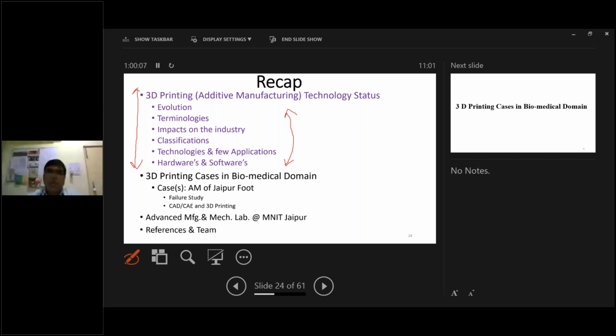Based on whatever scanner knowledge I have, the one limitation with scanners is the reflectivity of the light. If you have a material which is highly reflective, then it will be difficult. There are some powders which come along with your scanner. Just spray those powders on it, and then scan it. It should not be a problem unless the reflectivity is an issue, because this captures only the contours and the shape. It won't give you the internal material properties that you have to integrate into your CAD model. So you can scan a clay model, you can scan composite material also, as long as they are not reflective.